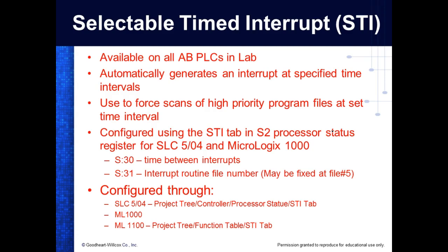But what we can do here is set up an interrupt called a selectable time interrupt, where we specify how often we want to go out there and run this interrupt service. So I have one set up for this PLC right here. Configure the STI tab. MicroLogix 500.